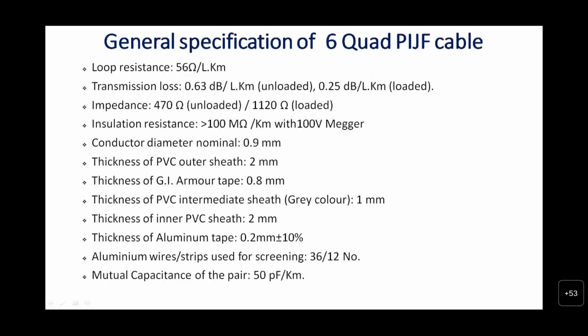So actually, in most of our South Central Railway, control is being run mostly through OFC, and quad cable is being used only for block and LC gate communication, IB phone and EC communication. So the majority of the quad cable is restricted only to block, EC, LC and IB phones.